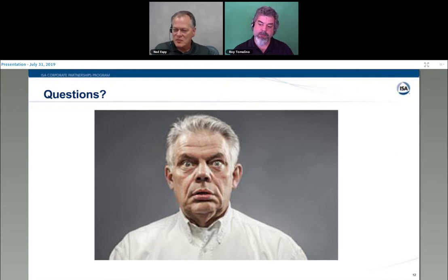So, gentlemen, Brian is asking, what's the lifetime on an RTD? It all depends on your process. If you have a harsh process, and the construction of the RTD, I guess the more rugged an RTD is made, perhaps the less accurate or the less responsive it is.